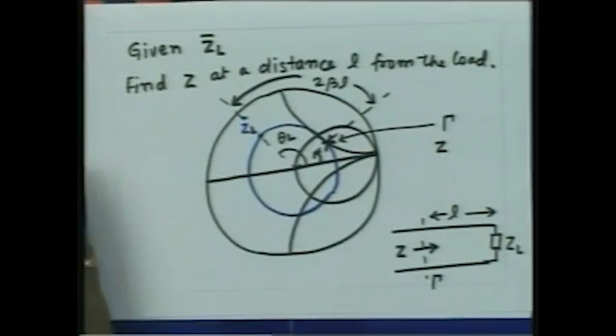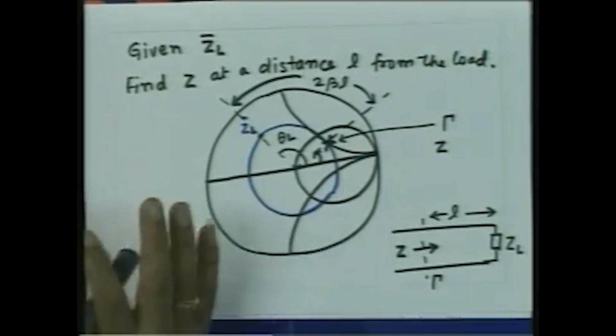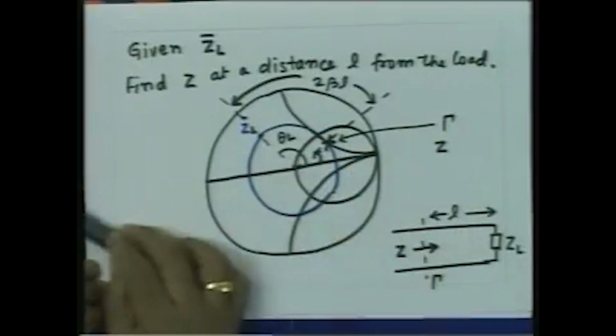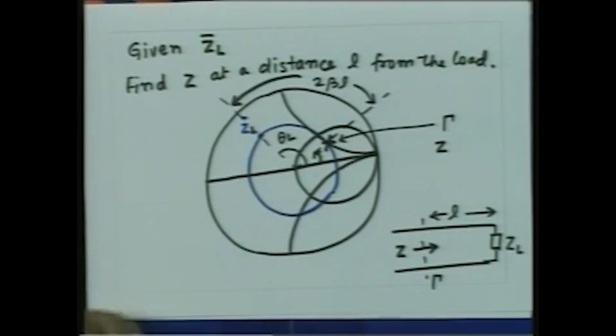So, the transformation of impedance or admittance is exactly identical on the Smith chart. Only, as we saw earlier, if I have to find the phase of the reflection coefficient, then the marking of the reflection coefficient axis comes into the picture, and then you have to remember that for the impedances the real axis is rightwards, whereas for the admittances the real axis is leftward. But otherwise, for impedance transformation calculations, once the impedance and admittance are normalized, the procedure for the transformation is exactly identical.